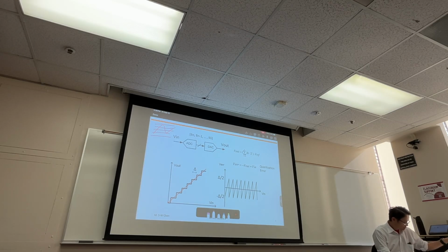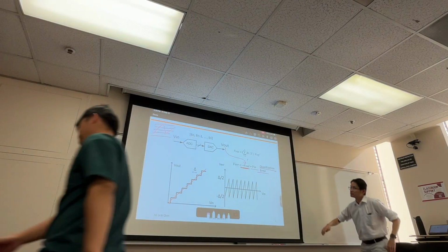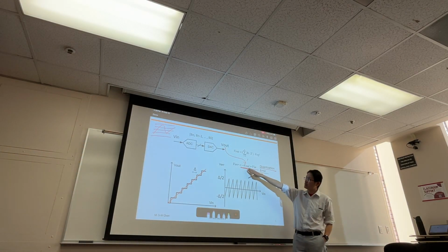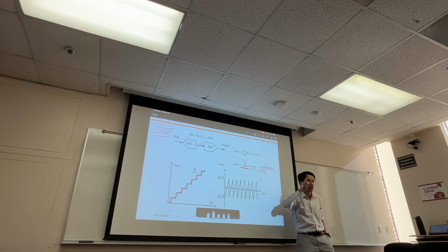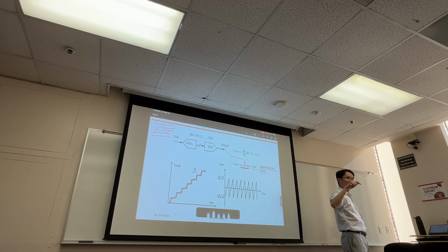Okay. So, in reality, by the way, this is what we define as a quantization error. From now on, we define the difference between the input and the output. This output is this output. We assume there's a perfect DAC at the output. We reconstruct based on your ADC code, and we look at the delta between the actual analog input and that V out. That's our quantization error.